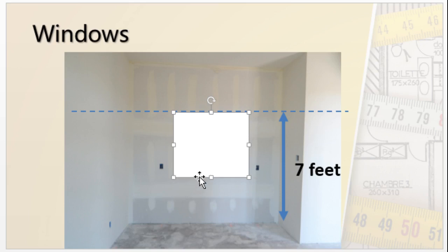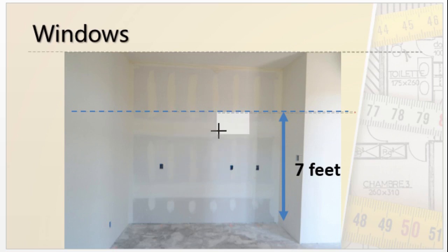If this is a bedroom window, this might be a kitchen window if it is 4 feet height. Previously the bedroom was 4 feet height and width might be 5 feet. For a toilet it might be a square window, 1.5 feet by 1.5 feet, like this. But whatever the dimension is, most commonly we start from above the 7 feet window reference line, and then we can take different kinds of windows based on our requirement. So this is the basic window we generally use.